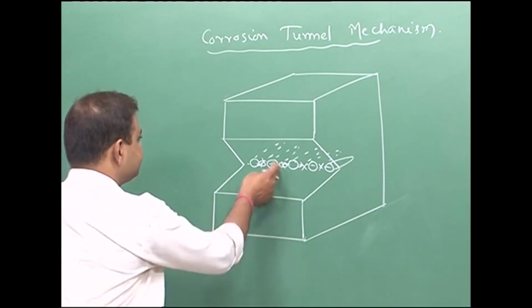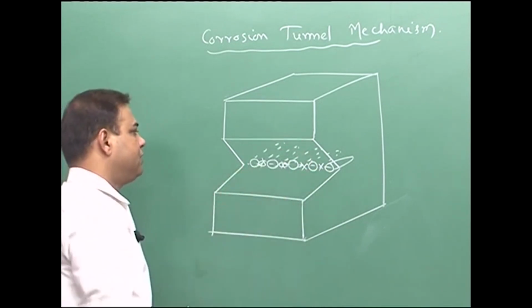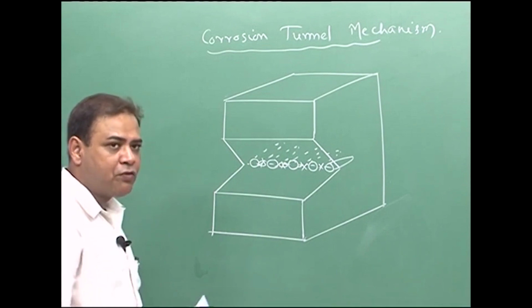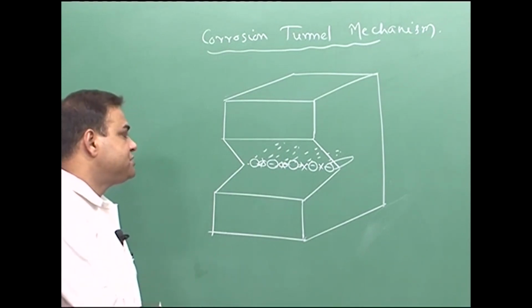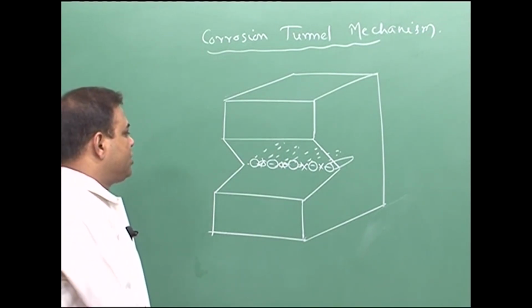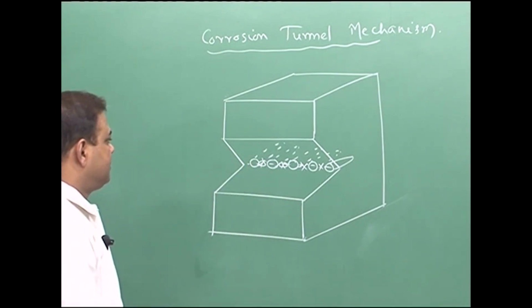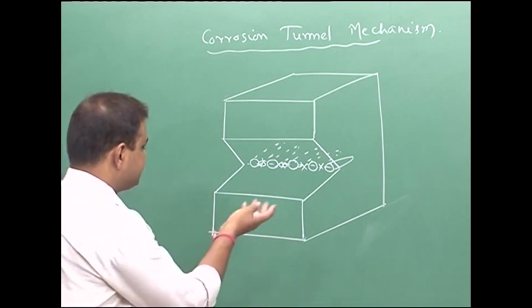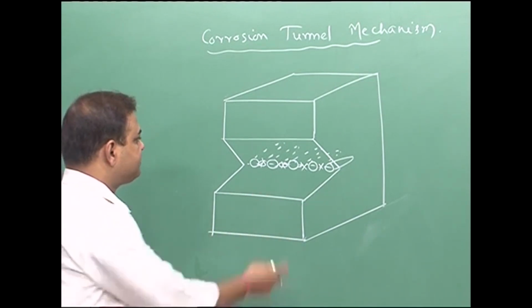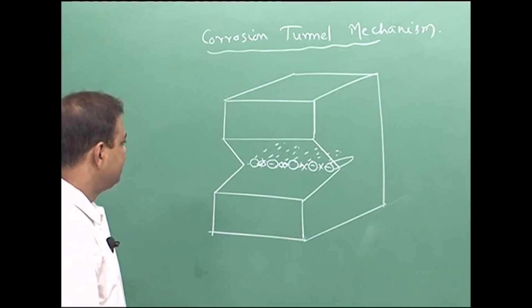But we do not experience any ductile failure or dimple nature, which is due to micro void creation and coalescence. In order to explain the matching surfaces, which is the result of SCC, this model has been modified.